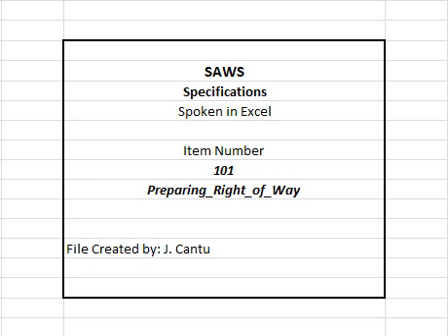6. Holes remaining after removal of all obstructions, objectionable materials, vegetation, etc., shall be backfilled and tamped as directed by the SAWS inspector, and the entire area shall be bladed to prevent ponding of water and to provide drainage. In areas that are to be immediately excavated, backfilling and blading may be eliminated, if approved by the SAWS inspector.